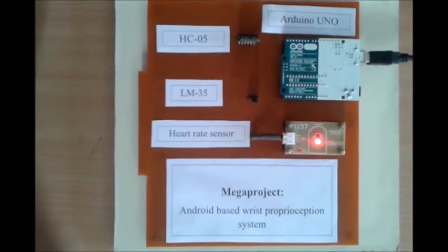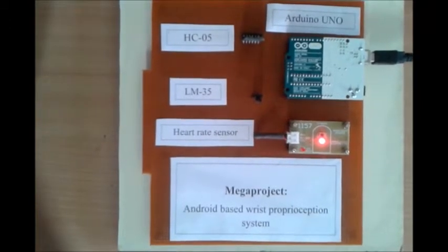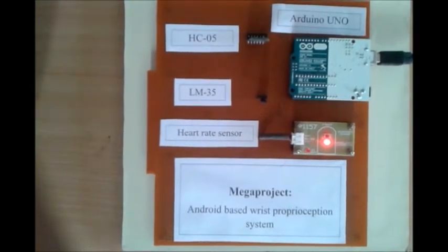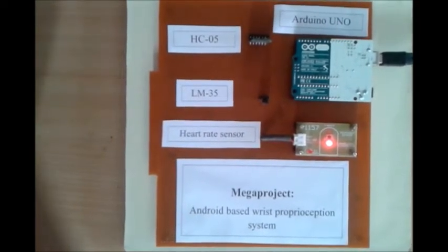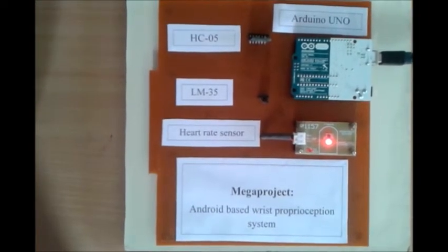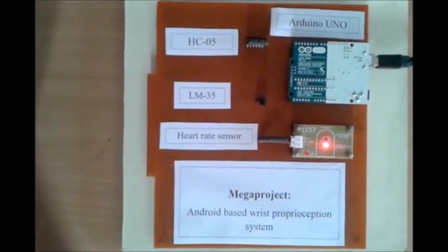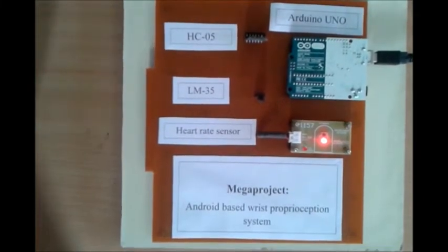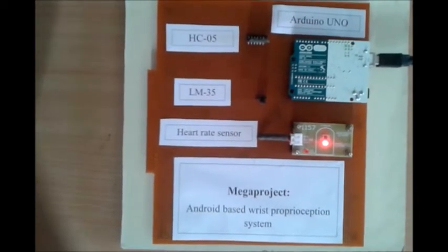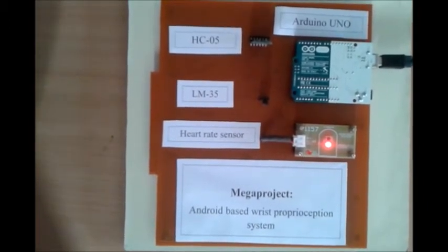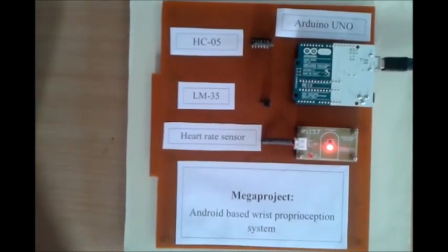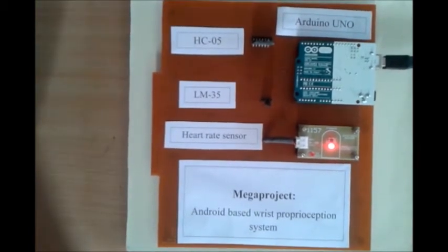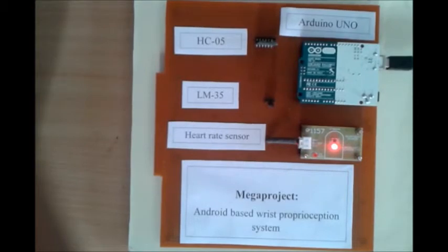In Arduino, temperature and the signal are stored in separate variables. The signal of LM35 is converted into temperature by a formula. The formula is: the digital value is multiplied by 5 and 100 and then divided by 1024. Obviously, 1024 is the sampling data. Now for the pulse sensor, it is compared with a predefined threshold. When it crosses the threshold, it is checked whether it is noise or pulse. If it is a pulse, then it is stored in the variable. Also, the running signal is stored in a variable.